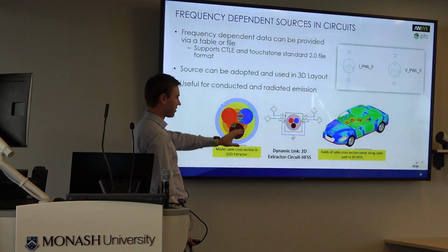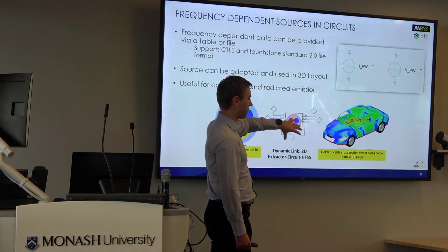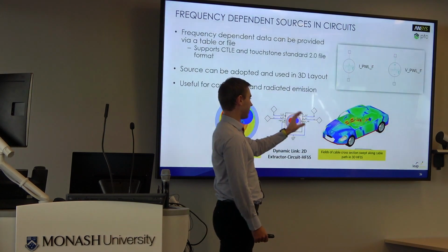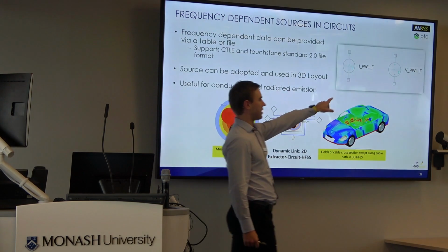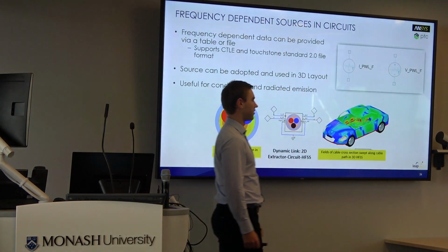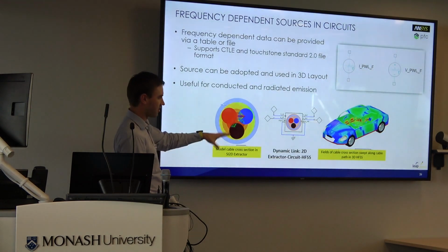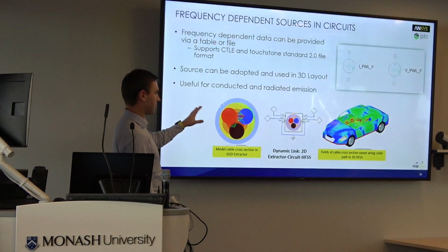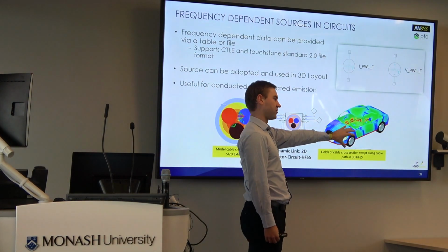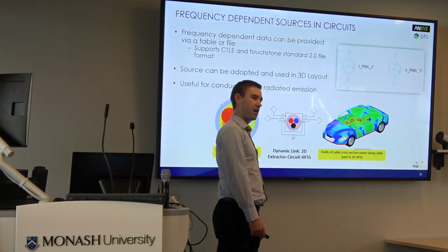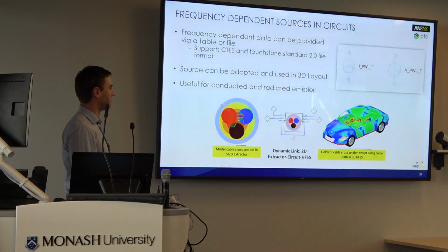Now the way we do it is we break the process in the middle. You can take your cable into HFSS as per normal, but rather than always having to look at the circuit, you just have ports connected to excitations like this. And so you can now do whatever you like in the circuit world, export a new set of frequency dependent excitations, load them into the circuit, excite the last mesh you created in HFSS, and we'll re-update everything in one go. No more having to resolve the huge process all over again.